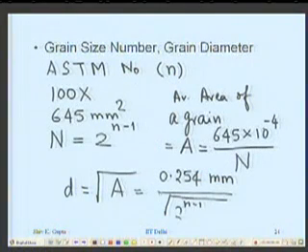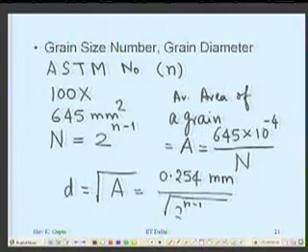So this is a magnification of 100 linear. I told you the areal magnification would be square of this. So I have multiplied the 10 to the minus 4 to make it actual millimeters square, right? So this is the actual millimeter square as a number n, because you can't see at that actual size. It's too small. So we magnify it 100 times. 1 millimeter length becomes 100 millimeter. But 1 millimeter square would become 10 to the power 4 millimeter square. Is that clear? That's what it is. Is this clear now? Right.